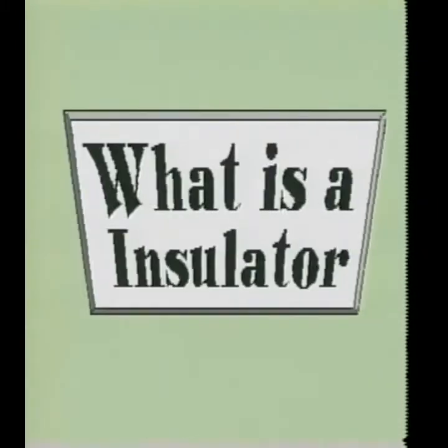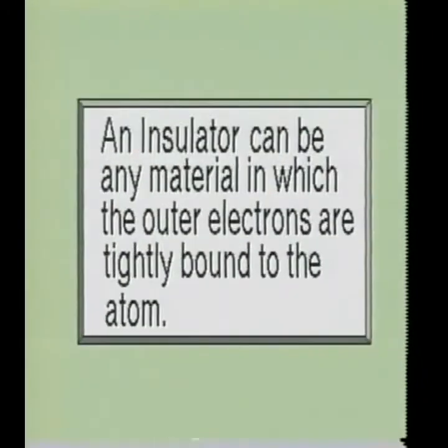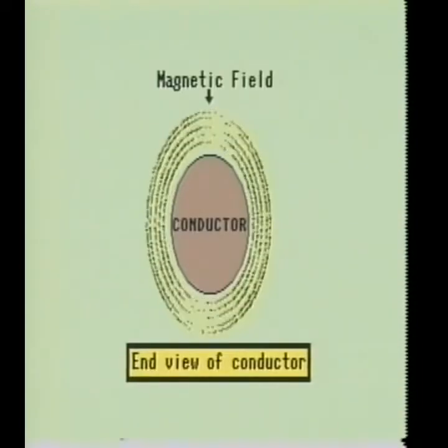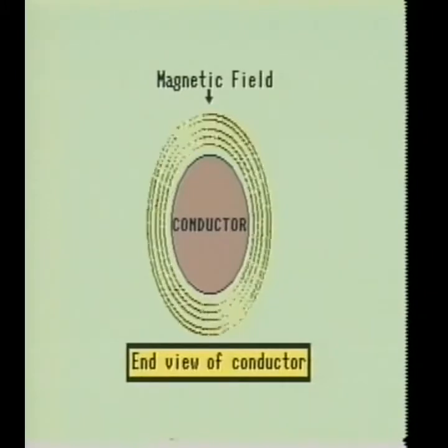On the other hand, an insulator is a material which electrons pass through poorly or not at all. Insulators include such materials as glass, plastic, wood, rubber, mica, porcelain, leather, and paper. Insulators are used to insulate voltages from ground potentials and other devices. Insulators are used on electrical devices for our protection, as well as to protect the device from shorting to ground and damaging the circuit.